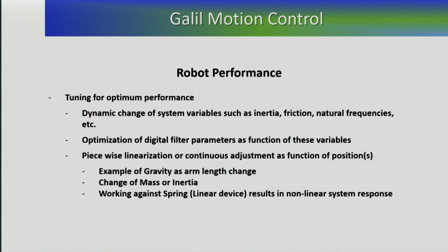Once you have the system, the assumption is that we now talk about integrating and starting to look at tuning PID parameters. With the PID parameters, you have to select for an optimum response. You want to have a system that's accurate. Ultimately, the purpose of having a robot is maintaining the highest level of repeatability. So accuracy and repeatability are achieved through optimization of your PID filters.